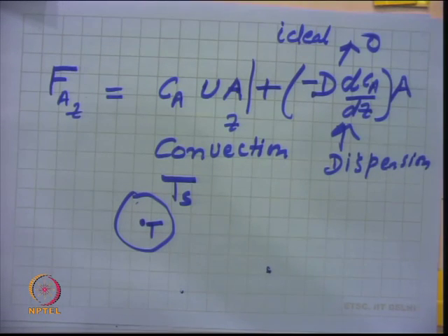So, this is something like a non-isothermal parameter, and you need to calculate it, because this will be a function of temperature, like the Arrhenius parameter we discussed, E upon RT. All these factors are important when you look at the temperature or thermal gradient in a pellet, and that is also to be checked, because beyond the maximum stable temperature the catalyst will become unstable or will sinter. We have to avoid that temperature. So, hot spot formation is to be avoided, and for that you need to work on the temperature gradient or temperature difference in a pellet.